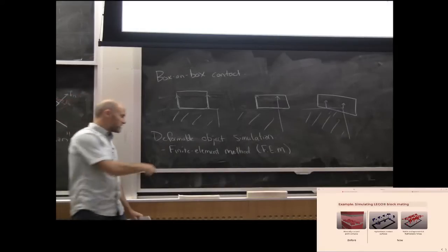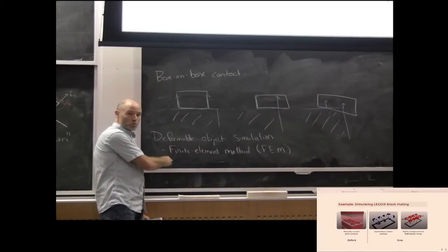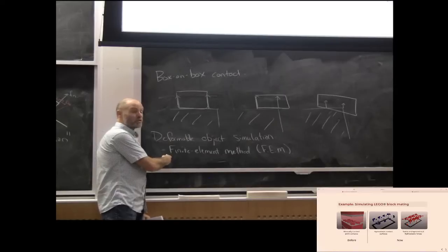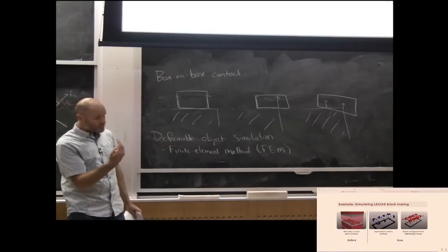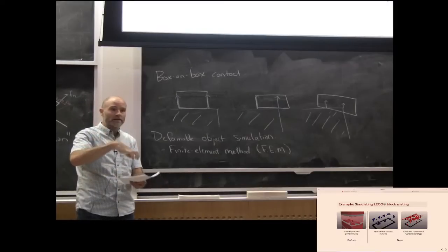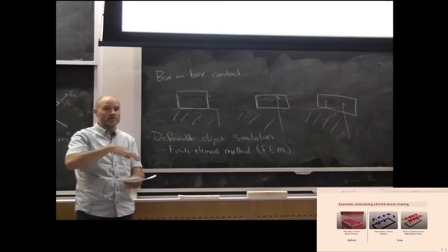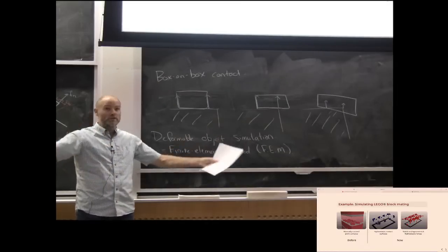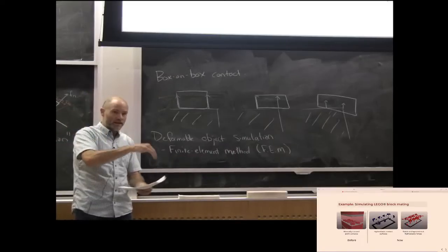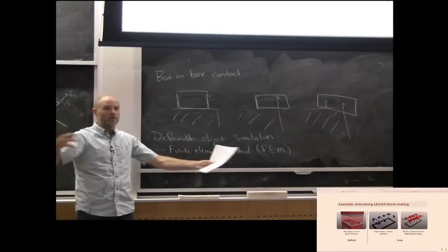So the question was, can we make finite element real time? I think people definitely have and can. GPU is a big accelerator for FEM type models, whereas contact is not optimized well by GPU because it's very branchy, in the sense that you take a different path through the code depending on whether you're making contact between object 1 and object 3 or not.